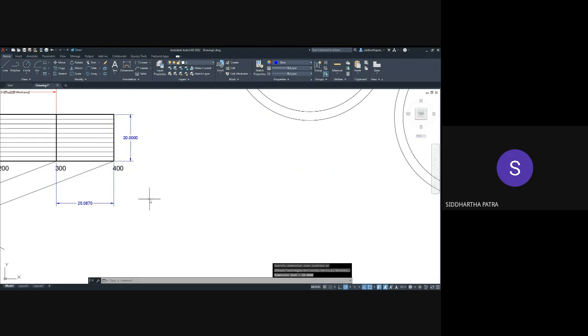What does that mean? I did a horizontal dimension, I did a vertical dimension. The dimension is put in the middle of the arrow. So, the arrow with two arrowheads. The dimension line, the arrow that represents the dimension, we erase some portion of the arrow, and in between we put the value of the dimension. And if it is in millimeter, we don't actually write the unit.